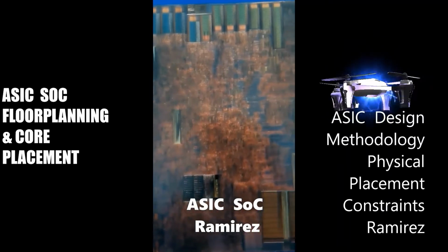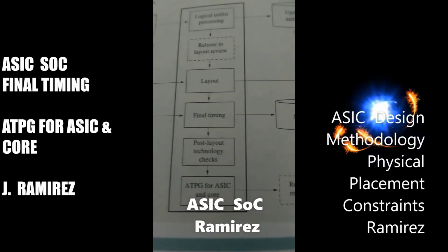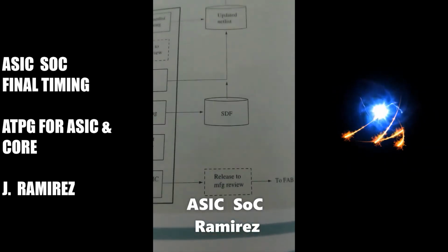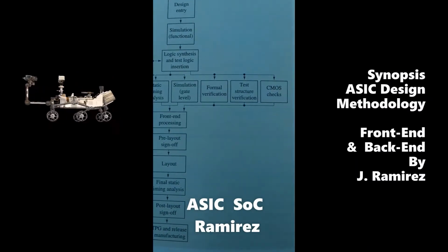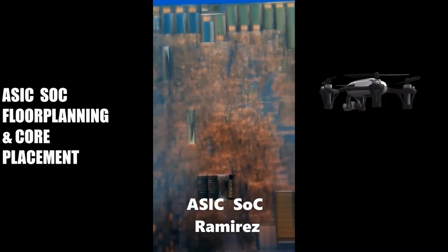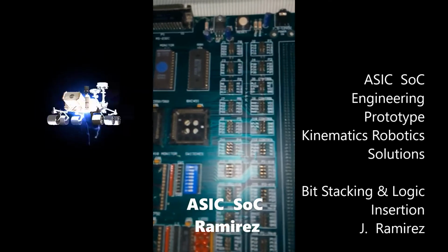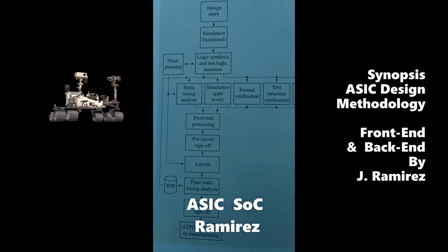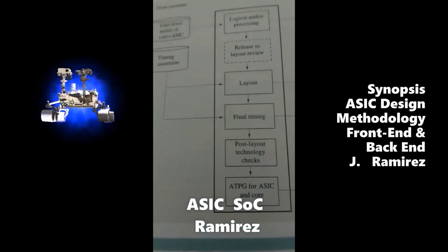Placement constraints. The area planner analyzes the distribution of the shapes and sizes of the library cells that take place in each macrocell and determines an optimal periodicity of circuit rows or columns and creates the placement structures based on each macrocell. This enables the placement functions to operate independently on different macrocells.